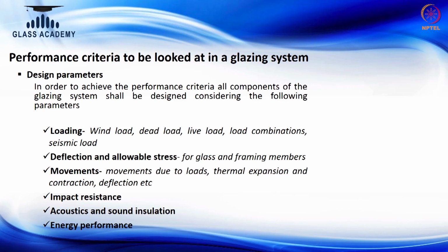We also need to understand the deflection and the allowable stresses permitted for both the glass and the frames. What kind of movement is being designed for: whether there is a provision to move horizontally during earthquakes, or vertically during higher wind speed or high deflection of the glass, and whether the frame has a tendency to adapt to it. What impact resistance can the frame withstand, what acoustic possibility can be introduced into the system, and what energy savings can be achieved even through the frame? Traditional box sections are very poor in U value, but today thermal break systems are available which help reduce the amount of heat coming in, not only from the glass but also from the system.